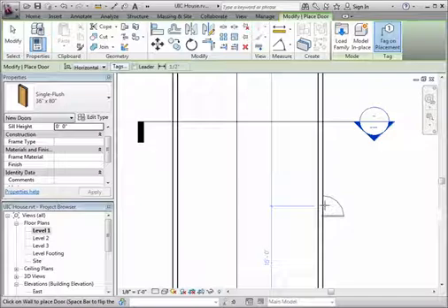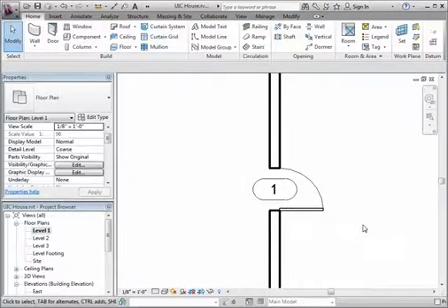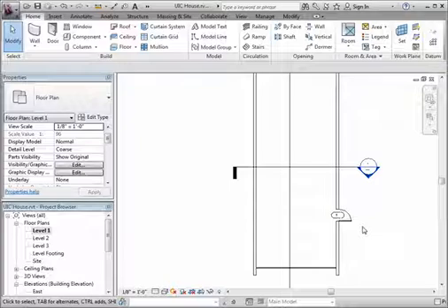And keep this here. See that Revit actually wants to tag that door. I don't need to see the tag, so I'm going to turn it off, which is another interesting topic. When you're working in CAD, everything is organized in layers, so you can turn things on and off and control what you can see. Revit doesn't really have any use for layers. Instead, since it's all family-based, you can choose to turn off all the doors, or all the door tags.